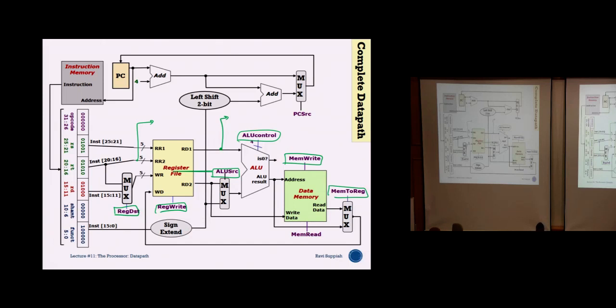So after the ALU, let's say just now you say register 7 and register 8, for example. After you add, why does it go into data memory? Because that is hardwired already. Hardwired means there's already a wire that takes the ALU result and sends it to the address. Because we do not know whether it's going to be an add or subtract instruction or a load word or store word instruction, I sort of do both together, and then later on the multiplexer and the MemToReg pin will tell me which one I need to look at.